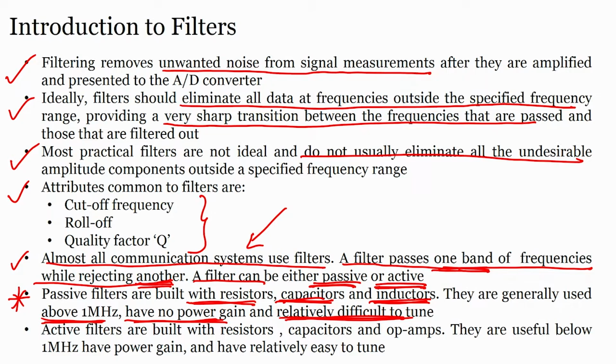No power gain because there is no op amp, no transistors, no active components, and there is no feedback. We cannot change the gain. There is no power gain. It is difficult to tune, and generally they are not used at extremely low frequency, right.